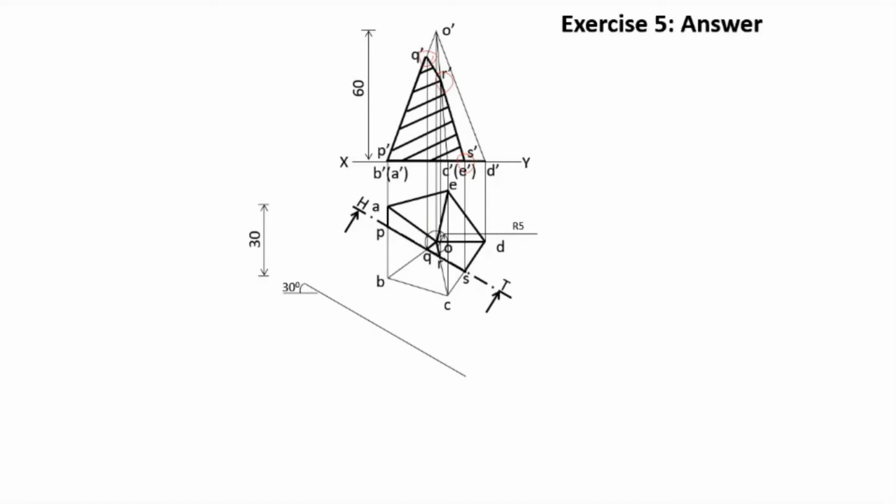Now, in the front view, this much portion is the sectioned surface. Now this part is also remaining there, so that the apex is remaining there, the point D is remaining there, so that also you have to draw as darker lines. So this much is the front view.